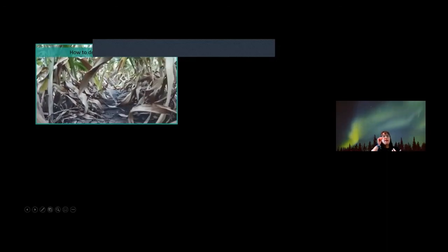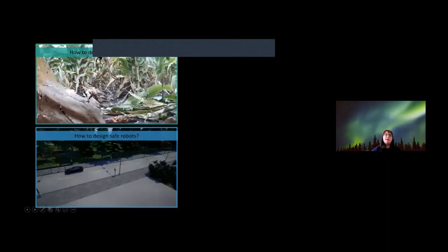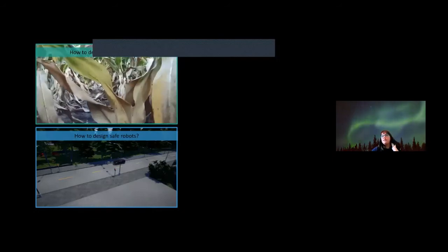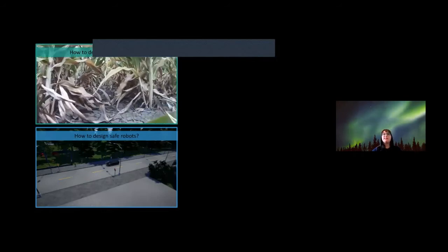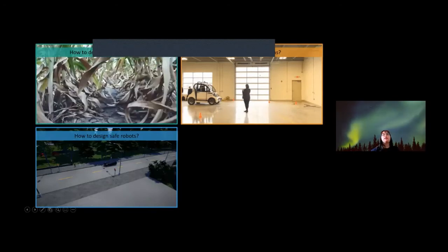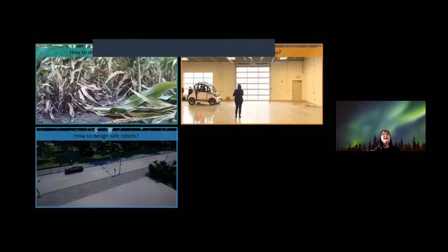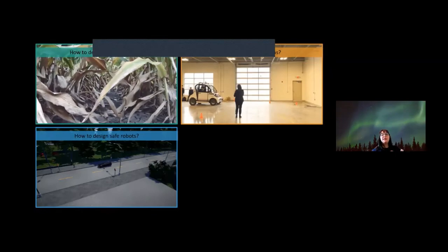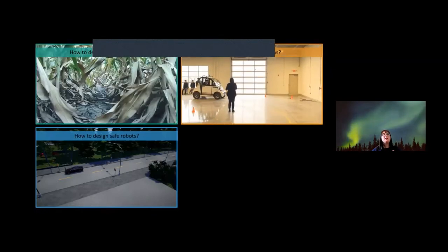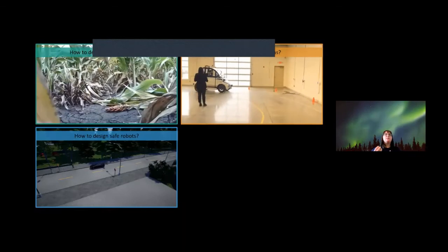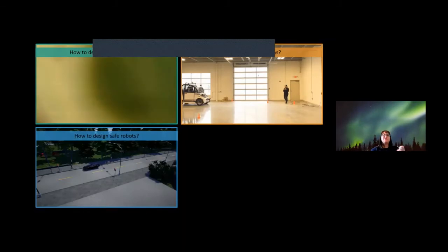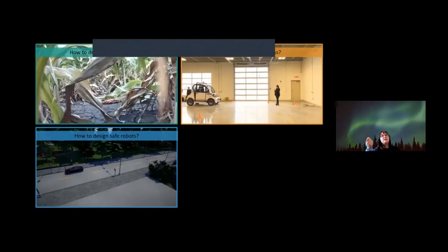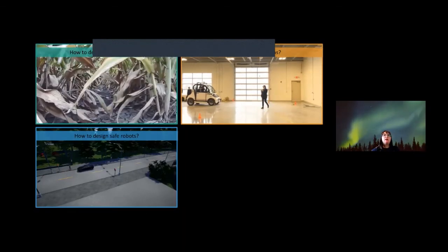Also on the robot side, I think about the safety components, again leaning into some of those simulation components. So thinking about how we can design for safety as well as assess it. One of the key pieces that goes into that is thinking about how to model the different human agents. Because if we want these systems to go out into the public and interact with these agents, we need a good understanding of how people will move through space. This is a quick example of a small autonomous vehicle where we're predicting how this human will move, and we're planning our motions around that.